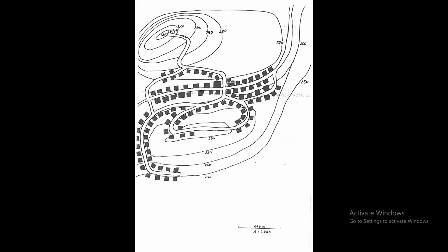In this design, you see that the highest point is somewhere here, and is at 320. And the lowest point is at 250. So if we do 320 minus 250, that will give you 70. That 70 gives the pressure of the zone. We say that pressure must not be more than 8 bars. They must limit it to 8 bars.